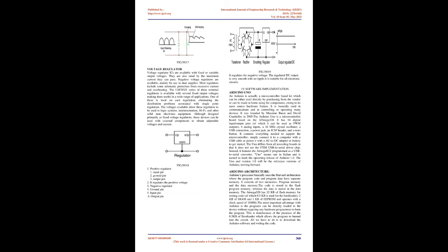The reservoir capacitor is large electrolytic, usually of several hundred or even 1,000 or more microfarads, especially in mains frequency PSUs. This very large value of capacitance is required because the reservoir capacitor, when charged, must provide enough DC to maintain a steady PSU output in the absence of an input current, i.e. during the gaps between the positive half cycles when the rectifier is not conducting.